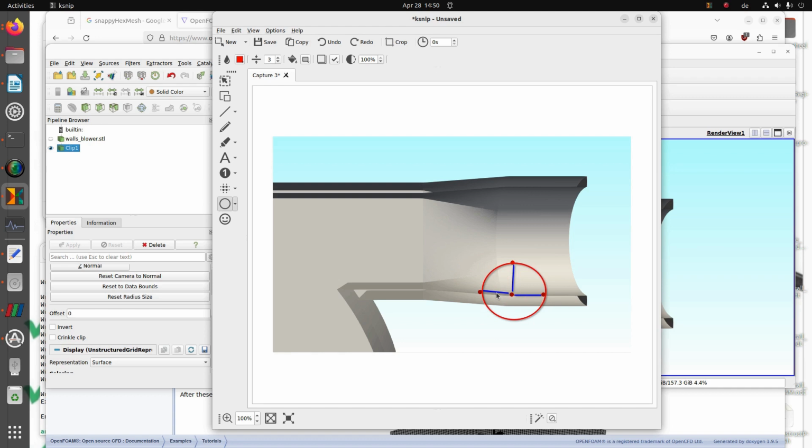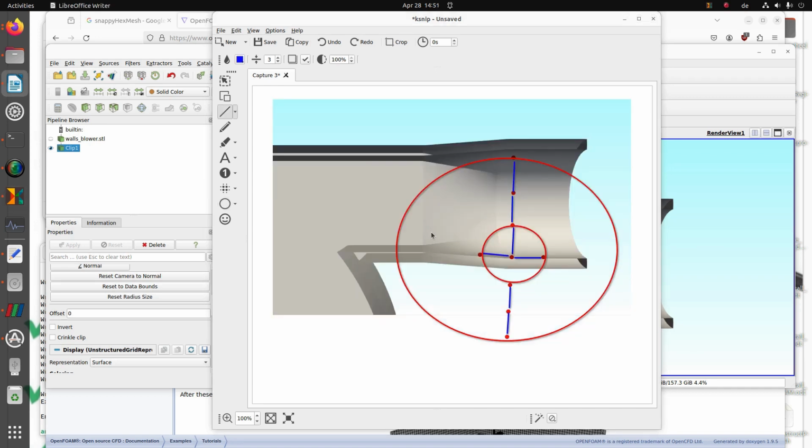So around. If you have a point in a mesh where fluid flows between two plates, it can happen with the larger tolerance specification, for example, like the next radius. It can happen that this area will be closed because the cells automatically jump to the opposite side of the plate and close the gap.